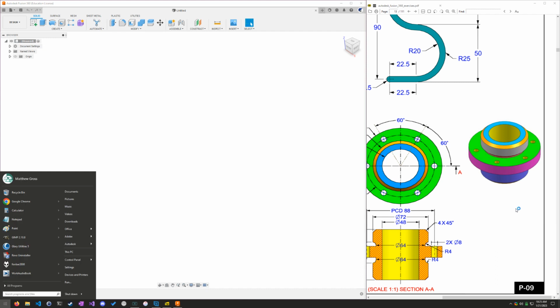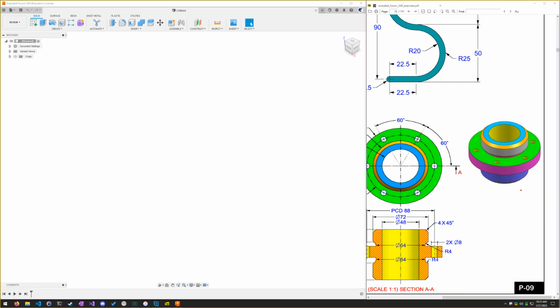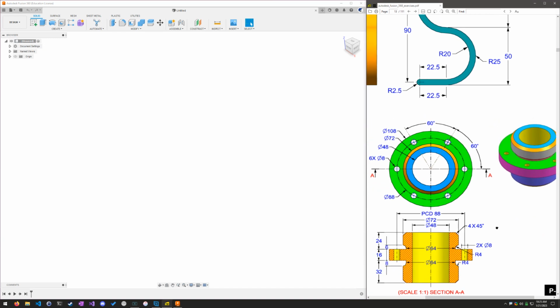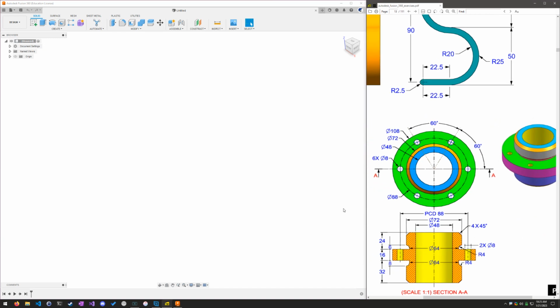if you're still kind of new to 3D modeling, you might be tempted to build this as a circle and then extrude up, and then maybe a bigger circle and extrude up, and then that smaller circle again and extrude up, almost like you're building a layer cake. But this is actually a perfect piece to practice using the revolve tool, which is to draw this halfway first and then basically sweep this part 360 degrees around so that it revolves around that central axis.